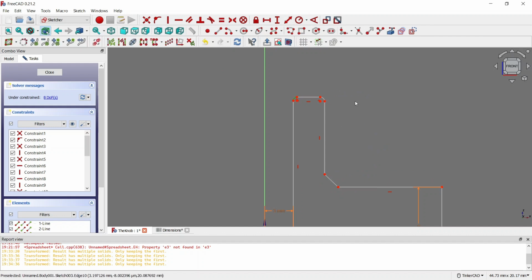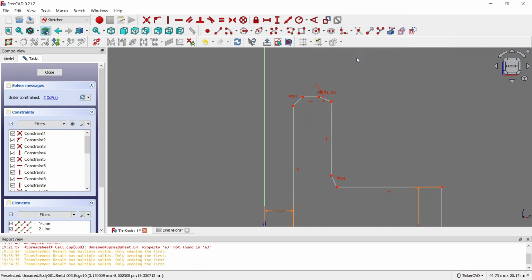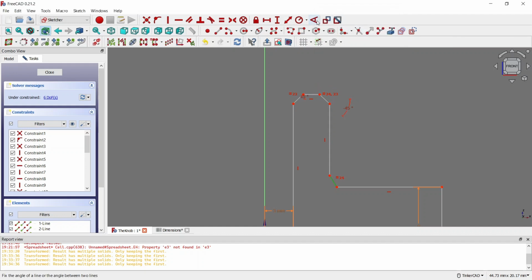So we have chamfers. Well, chamfers are basically easier to print with a 3D printer. What I also heard, when you try to make it in the CNC with aluminium, it's much easier to chamfer than to have a rounded edge or a fillet. It's basically cheaper to manufacture.